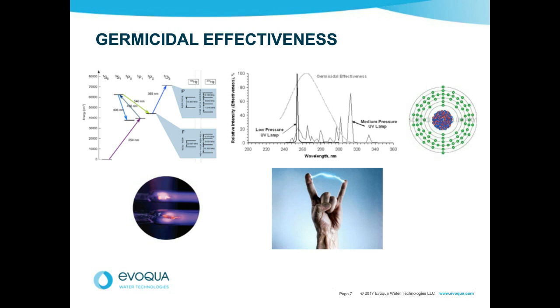We do a lot of work with brines. We do a lot of work with injection waters for platforms, a lot of UV on ferries, on vessels for ballast water disinfection. Lots of water is forced down hole for the oil companies. Lots of fracking now uses very high TDS, very concentrated brines. So the transmittance of the water is a critical factor. The path length between the lamps is therefore very important. We can't have one powerful lamp in a big fat chamber. You're better off having 6 or 7 lower powered lamps in a chamber, so we aren't trying to cast the UV too far. So the optical transmittance is more important than the conductivity.